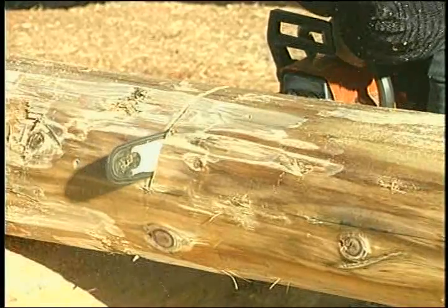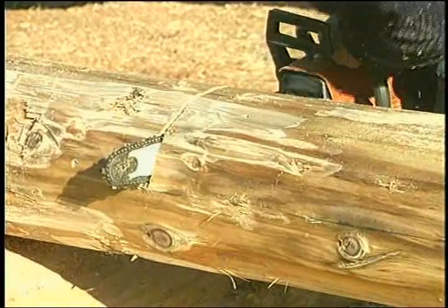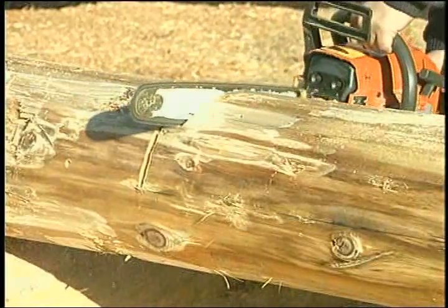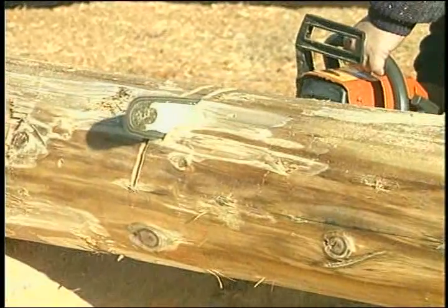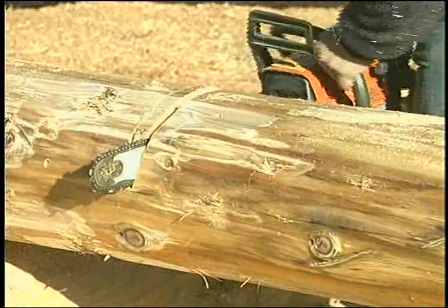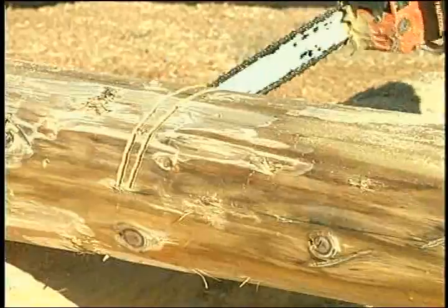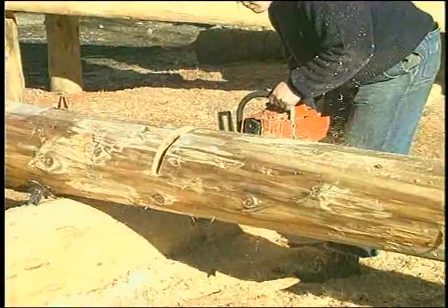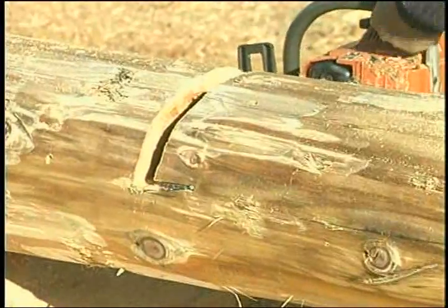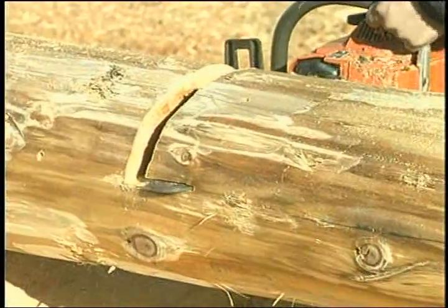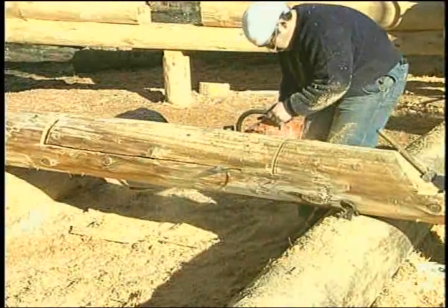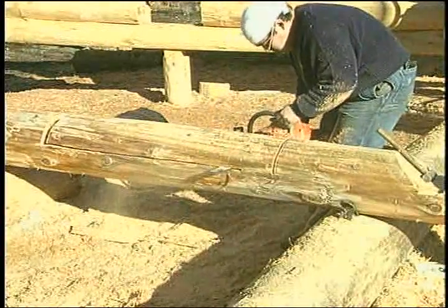Continue the cut to within 5 millimeters of the line and make sure that it's straight on the bottom. Now make a second cut right alongside this one and clean it out to the line. This will allow you to watch the tip of the saw as you plunge cut through. Then continue this cut to the end and, as usual, be cautious that you don't overcut any of the lines.